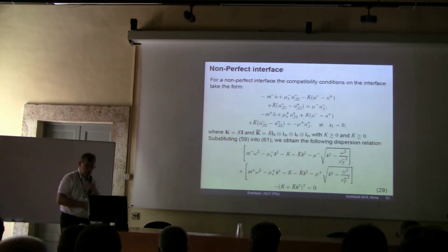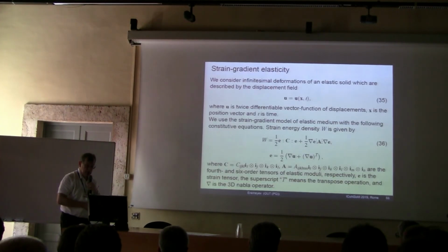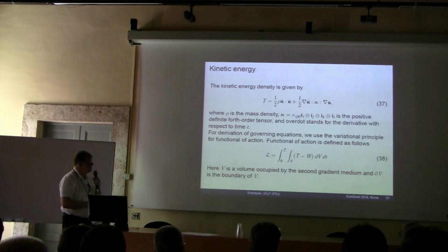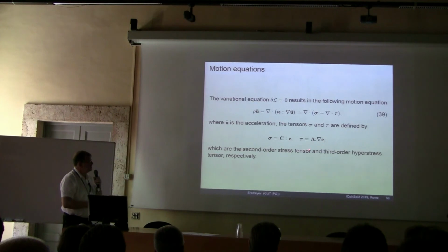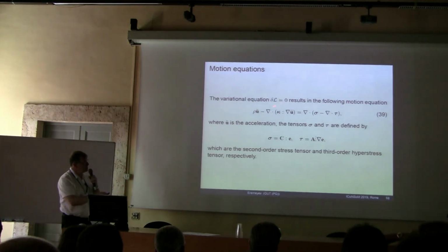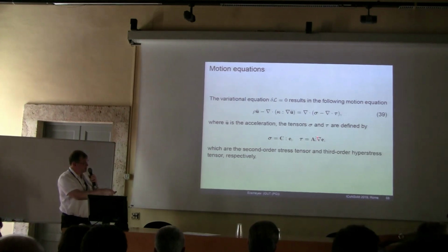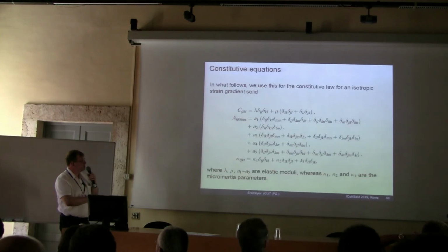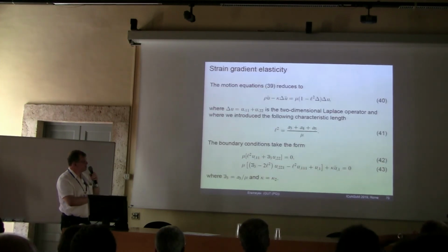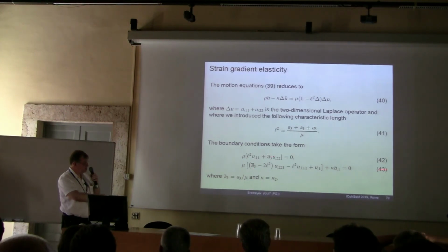For strain gradient elasticity of such kind, you can see that the motion equations look more complicated. You have these higher order inertia terms. You have higher order stresses. You have hyperstresses here, which depend on the second gradients. And the boundary conditions for these antiplane motions look like that.